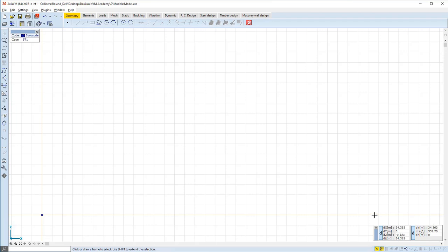From this point, the user has 3 options to start a modeling function. The most straightforward way is to define the start and end point graphically using the mouse as the main input device. In this mode, pressing Shift can help sticking to vertical or horizontal directions or pre-specified directions in between. The default value between each step is 15 degrees.